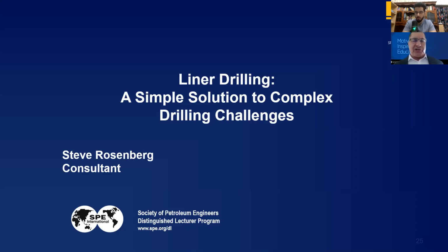Another technology it's compatible with is continuous flow circulation. The advantage of continuous flow circulation is that on connections, you're continuously pumping, which is great for drilling through depleted sands. So those two technologies are compatible. So it's a very versatile system. It's got its application.